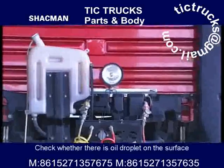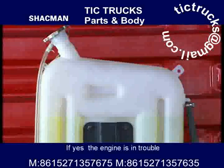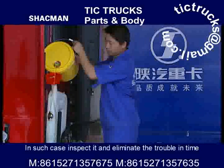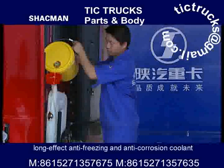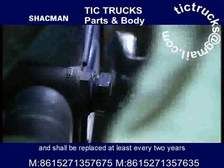Check whether there is oil droplet on the surface. If yes, the engine is in trouble. In such case, inspect it and eliminate the trouble in time. It is a kind of long-effect anti-freezing and anti-cooling coolant and shall be replaced at least every 2 years.